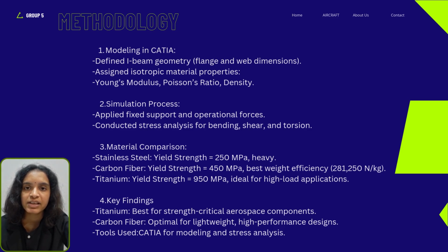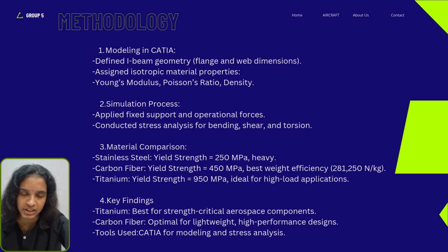To simulate real-world conditions, boundary conditions were applied to the I-beam model. Fixed supports were established on one end of the beam to represent typical constraints in aircraft structures. Operational forces were then applied to replicate realistic loading scenarios.